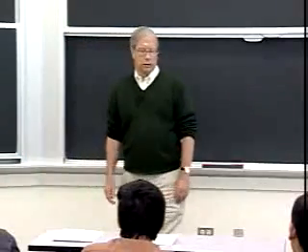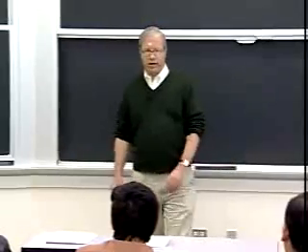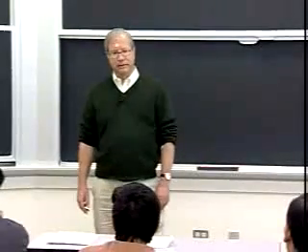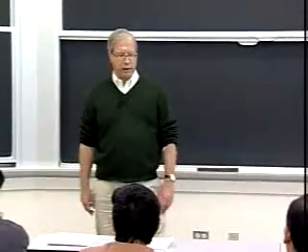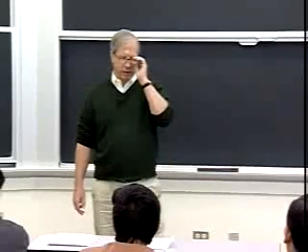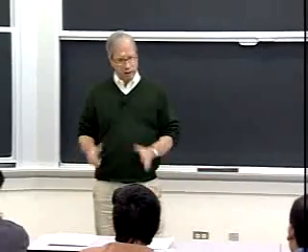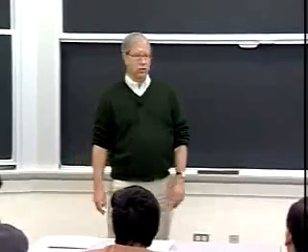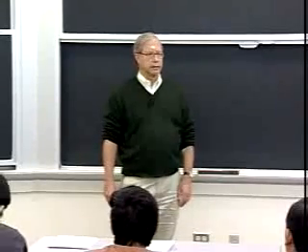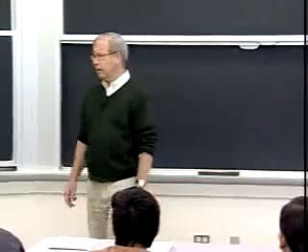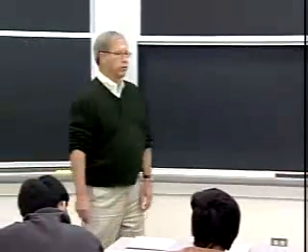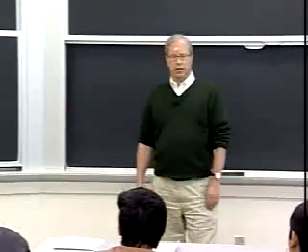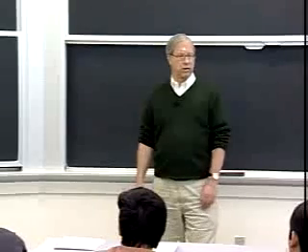All right, so, you know, there's a bit of a trade-off between an exact count and just getting a gross handle on the situation. But I say it certainly has got to exceed the branch complexity. So when I find the branch complexity goes up exponentially, even for one branch, then I know that the total Viterbi algorithm complexity has to go up exponentially with that. All right? So is that the whole story? Do we now have a pretty definitive handle on the, quote, complexity of at least maximum likelihood decoding, trellis decoding of a block code?